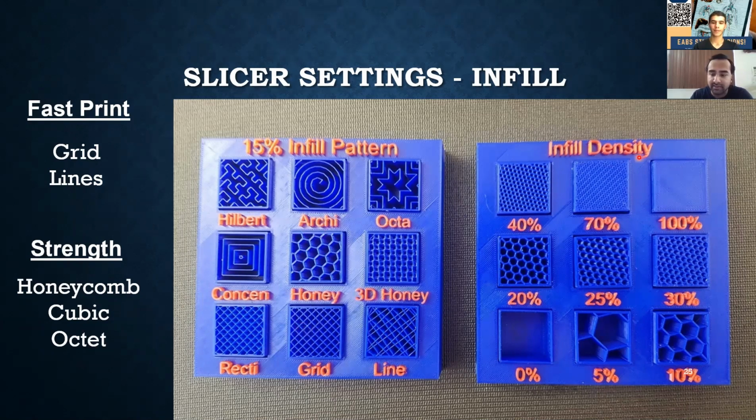You can also use infill density. 100% corresponds to the entire model being made out of your material, and generally that's overkill. Likewise, if you have 0%, you literally only have the edges of your model, and the inside is completely empty, which does not make for a very structurally rigid part. In my experience, pretty much 10% is ideal. You don't need to go beyond that. If you want, you can do 100% for some very small pieces where it doesn't make much of a difference to go 100 or 5 or 10. But as a default value, I always stick with just 10%. It just works for me.